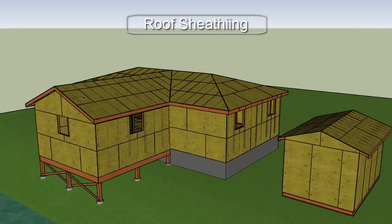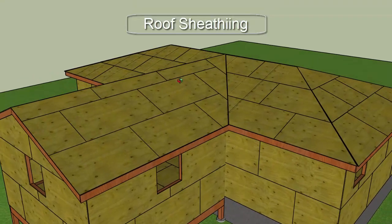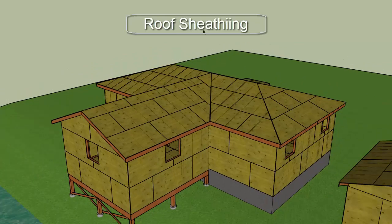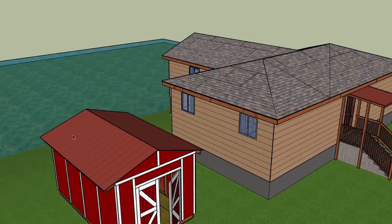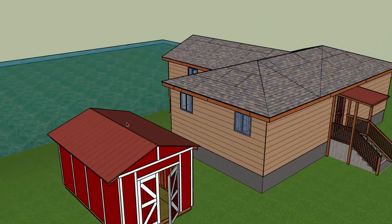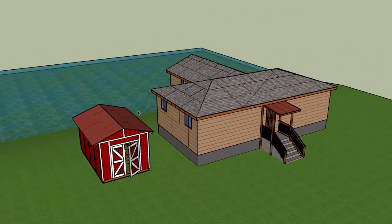Then our last component is our roof sheathing. Just like the wall sheathing, you typically want to use plywood that is 5/8 inch thick or greater. It's going to be laid out the same way as the floor and the walls were, staggering those joints in that brickwork fashion and spanning the long edge across as many rafters or trusses as possible. Then you can put on either an asphalt shingle roof or a metal roof. I've done fuel bladder roofs, water bladder roofs, whatever you can do with the materials you have available to you in order to make that roof watertight.